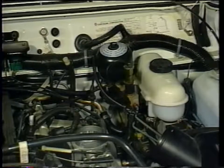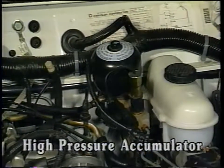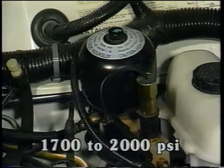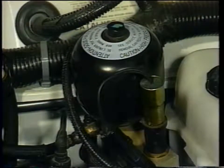This ABS system will contain 2 accumulators. The first one is a high-pressure accumulator that is nitrogen pre-charged to 1000 psi and is designed to store fluid at 1700 to 2000 psi. This accumulator is located on the master cylinder booster assembly.